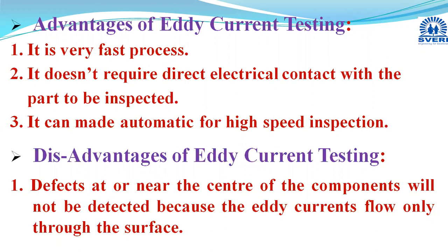Okay, and what are the disadvantages? The disadvantage of this method is that defects which are present exactly near the center area of that specimen cannot be detected, as eddy currents are not able to flow up to the center of that component. This is the disadvantage of eddy current testing. A defect which is present near the center or exactly at the center is not possible to detect with the help of this eddy current testing, because the flow of eddy current is restricted, meaning it cannot penetrate up to the center of the specimen.